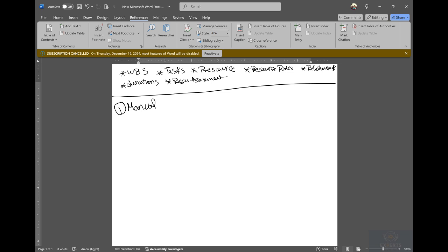Resource rates, which we have from procurement and from the RFQ and quotations. Relationship, this is from experience, and from the logic relationship between all the activities and the sequence of the work, which is coming from the discussion with the management and with the construction team, and with the method statement which is approved by the consultant.